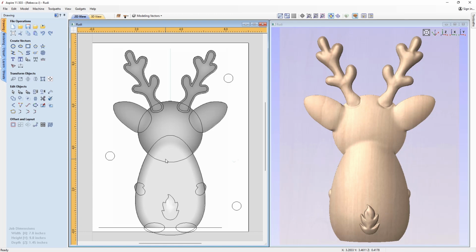If we had our dowels set up in a symmetrical fashion, for example, if you just had two that were opposite each other, you can run into the case of flipping that the wrong direction and then you end up cutting it the wrong way round. So this just ensures that you're never going to flip your part in the wrong direction, because there's only ever one possible way that you could locate the top side to the bottom side.